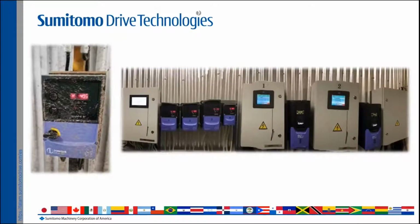Talking about suspended particles, maybe you will need a specific IP level of protection. For example, here in this example, we have two variants of Invertek drives. This one is IP66 rated protection. So this is completely sealed. It's protected against water and also dust, as you can see here.